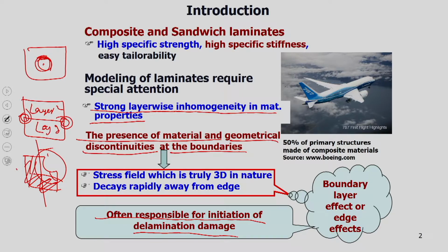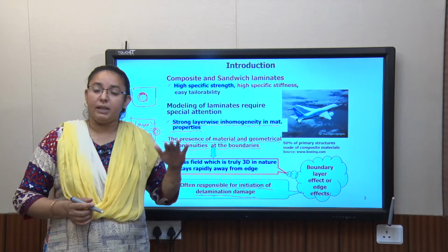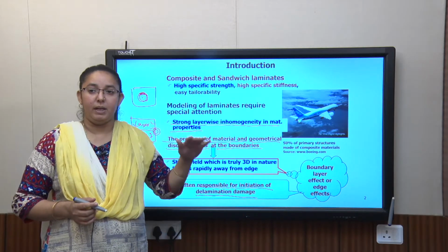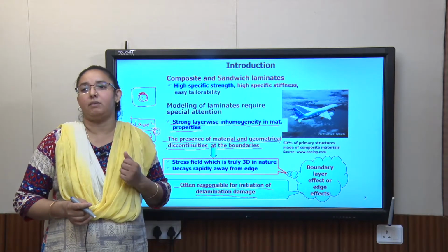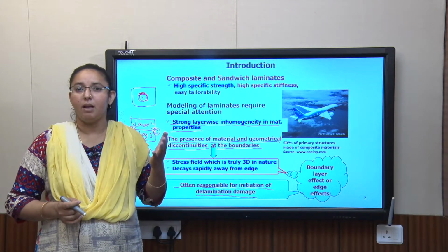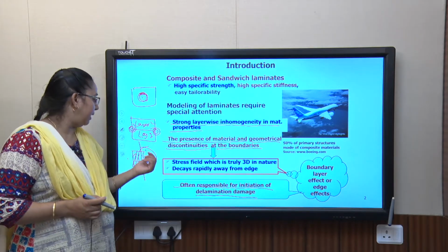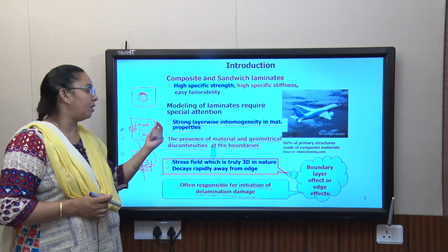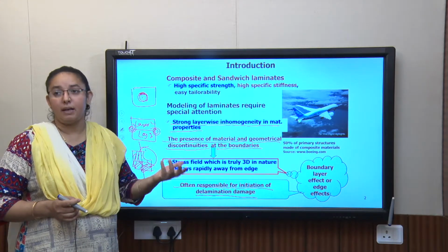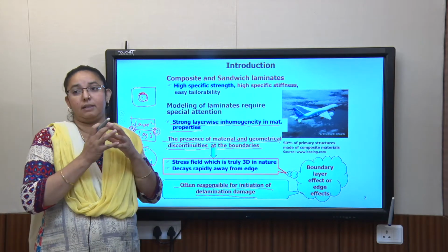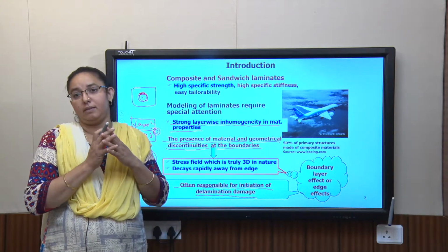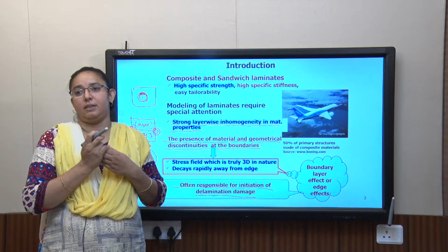crack propagation. So, when we subject these laminates to real conditions, they fail at a lower strength level. You design for something, but due to these stress singularities, edge effects or boundary effects, they fail early. So, we are interested to find out the exact stress behavior for those cases.